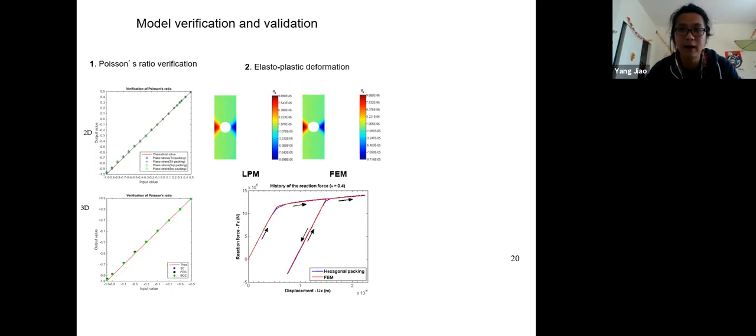But nonetheless, after calibration, we see that the current method can very well reproduce what has been produced using the best finite element simulation. There are some discrepancies if you look more closely around this turnover region where the material exhibits transition from elastic to plastic behavior. But again, that is because this model is not really fully a continuum-based model. It's a discrete model. So this is where you see some small deviations.